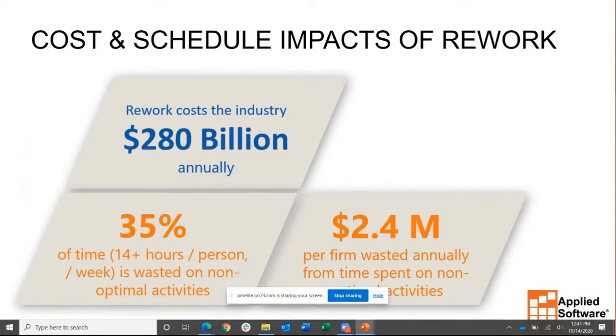And if you're going to do something twice, obviously there's going to be time associated with the rework. Any sort of rework would involve undoing work that you've done previously. And if it's a matter of undoing maybe some concrete that you've poured, that could be a really big deal. So it's important that we take a look at the cost and the effect of rework and how it affects the schedule.